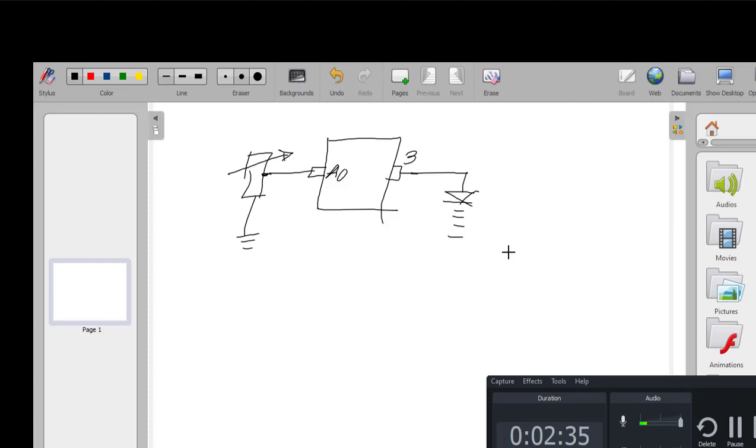This LED is one that is going to light depending on the different values of the duty cycle. Now, I just want to mention here, remember that we looked at the theory behind it, so let me just remind you a few things. So the voltage output that goes, in this case, for example, to the LED will be equal to the duty cycle multiplied by the voltage supply. In this case, the voltage supply is coming from the Arduino, and that's approximately 5 volts.